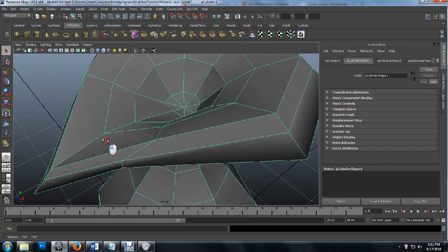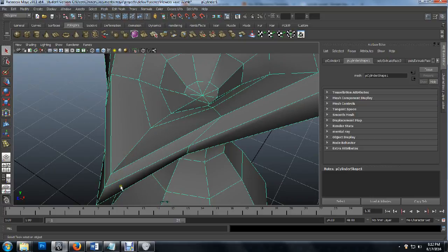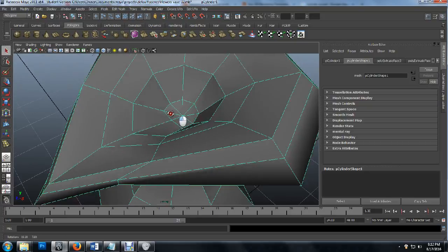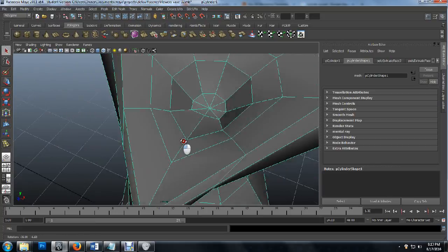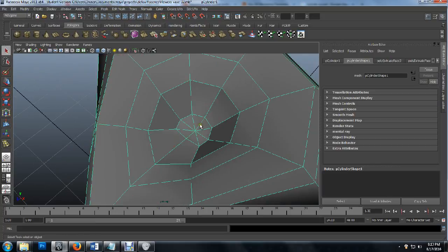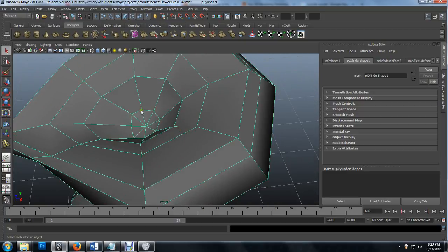And you can look at the way this little spout goes. We have a quad, a quad, a quad, a quad, and they all flow back. Nice, smooth, right? And then we get to here where there are these triangles. And all of a sudden it stops. That smoothness is gone. And these will actually create pinches and snags when we try to texture this. And if we wanted to do some animation with this, these triangles aren't going to animate as well. It's actually going to bend or tear the face when it comes to rendering.